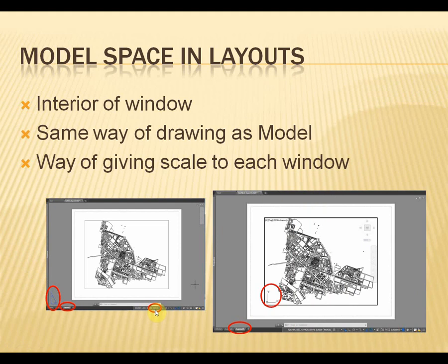When you go into the model space you have the layout activated, but instead of the triangle you have this symbol XY in each viewport. In this case you have only one viewport, so you have only one axis, but if you had more viewports you would have more symbols in each viewport. And you have the word model, so you are in the layout but in the model.